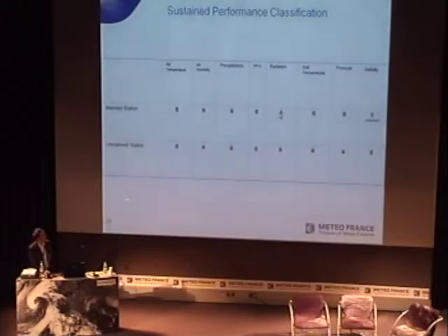The first one is the global radiation. We had examples by Laurent of some information before in the morning. And to meet the WMO requirements, you need to swipe the sensor every day to make sure it is really clean and there is no dust in there. So if you have nobody there to do this operation, you cannot meet the requirement of WMO.